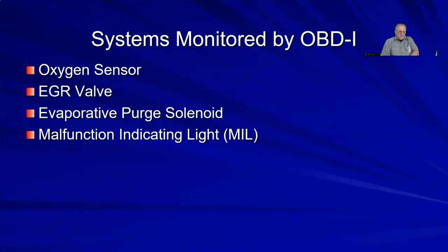Taking a look back at here. The oxygen sensor. So on the GM vehicles, they had a code 44, lean exhaust. Code 45, rich exhaust. Code 13, dead oxygen sensor. For the code 44 to set, your O2 sensor voltage had to drop below like 150 millivolts or 100 millivolts, and stay there for like 30 seconds.